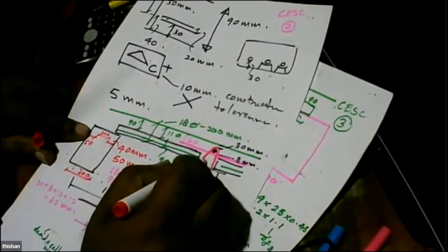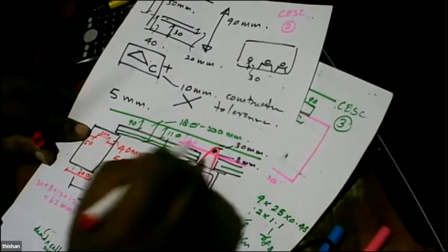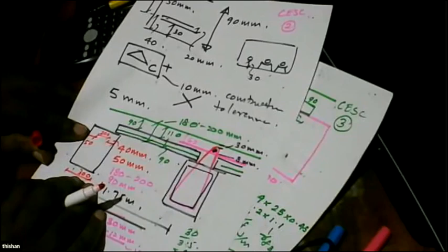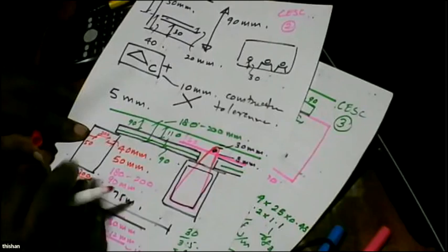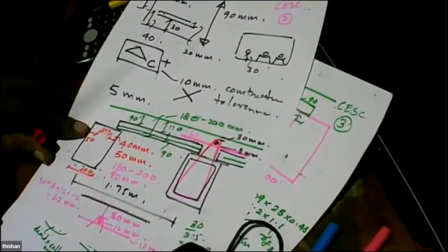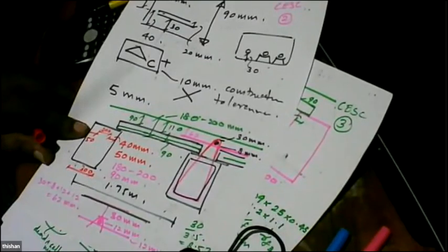Here you get a weak plane, and the idea is, you need reinforcement to resist that particular interface shear. And so for this type of loading, because we are reducing the total bending moments, interface shear also becomes smaller. Is that clear? Because interface shear is applicable only for the live loads, not for the dead loads. Dead loads are not taken using interface shear. Interface shear is applicable only for live loads, so that's why we are actually extending this particular link. I think, but you have to check it. There's no question, right?